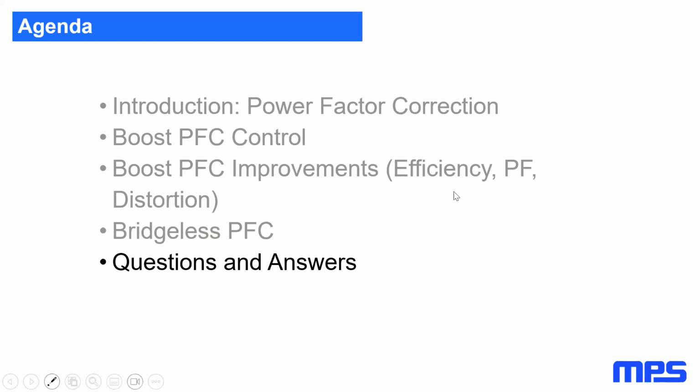And again, I'll give the same answer: depending on your exact needs and your target, also efficiency, cost, and so on, then maybe the silicon MOSFET is good enough, or maybe you need something that has a little less losses at the given point of operation. And then if GaN is not sufficient because the input voltage is too high, for example, then maybe silicon carbide is the solution. So it really depends on what you're trying to achieve.